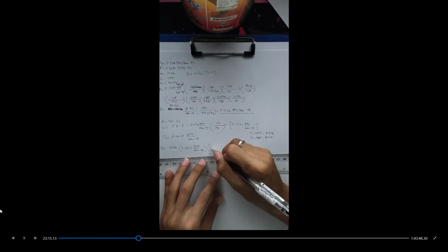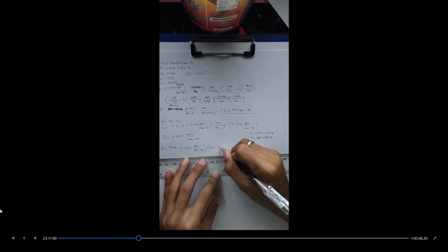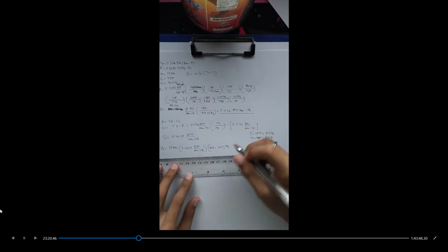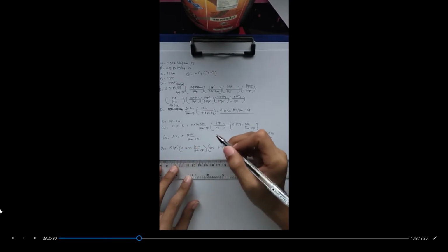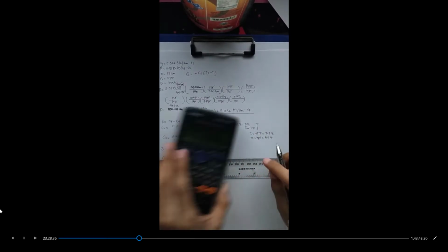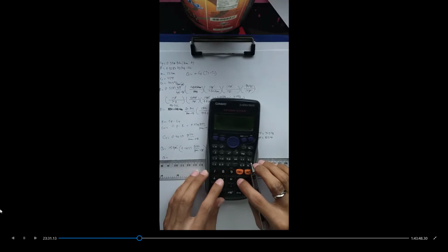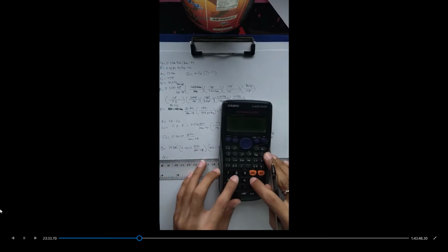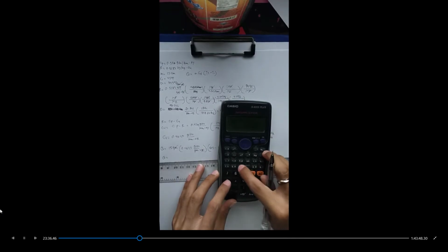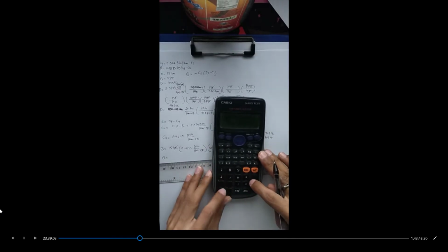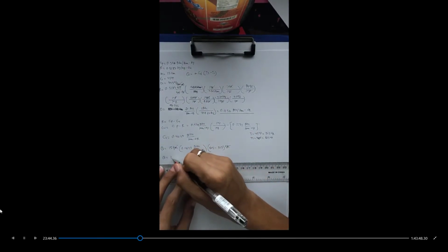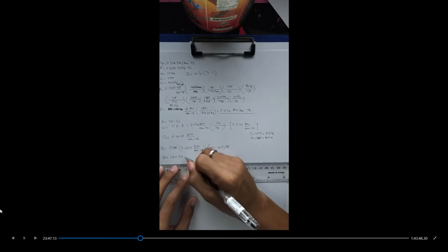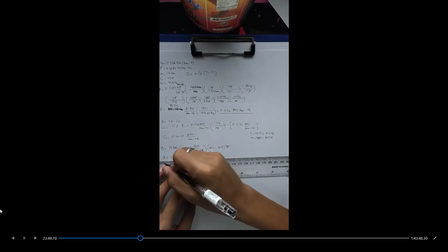Now, by substituting the values, 805 minus 505 degree Rankine, we need to cancel the units. Pound must cancel, Rankine cancel. We'll be left with the unit of heat, which is in BTU. Now, multiplying our constants, 15 times 0.4023 times 805 minus 505, the resulting value will be 1810.35 BTU. So that's for our problem number 3.